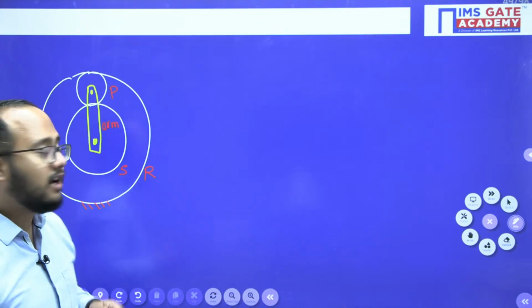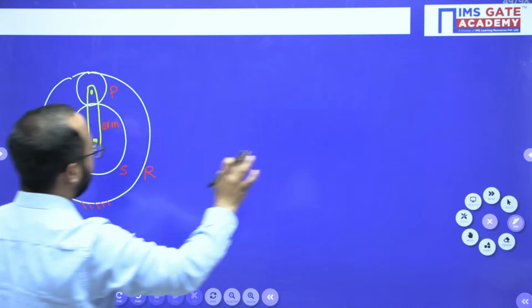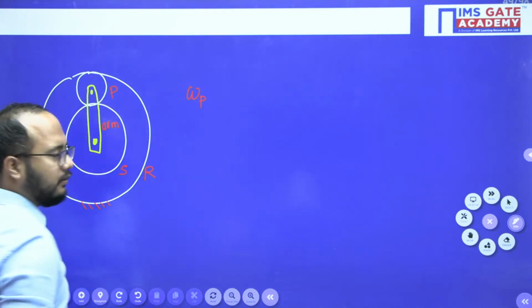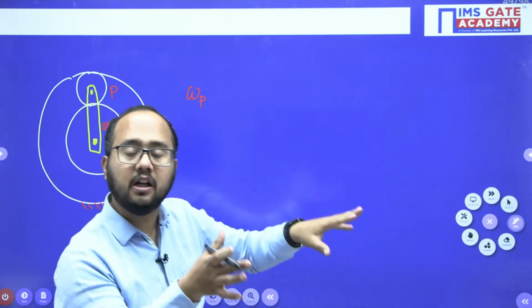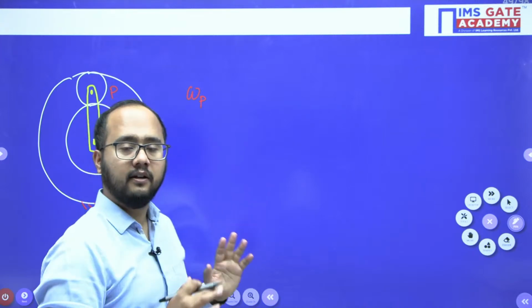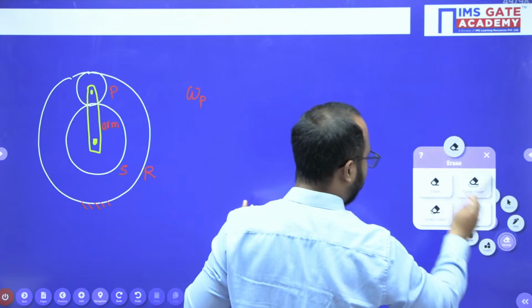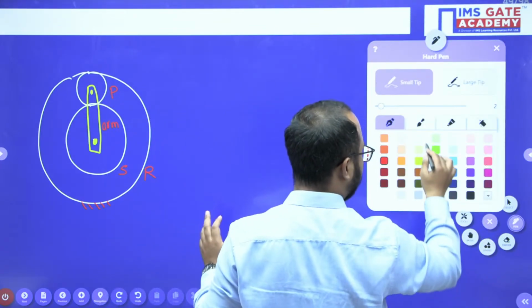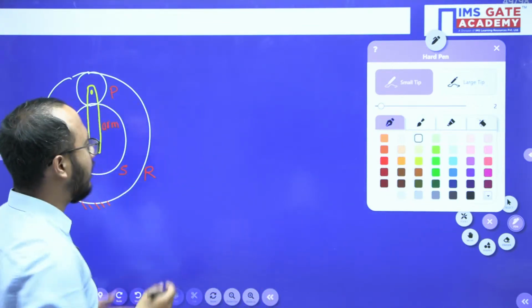So now consider this point very carefully. When I write here the velocity of planet gear, see, when I say relative velocity, you are considering any particular gear with respect to any other gear. For reference, you can consider any gear. But as far as the epicyclic gear train is concerned, I will take the reference of the arm.